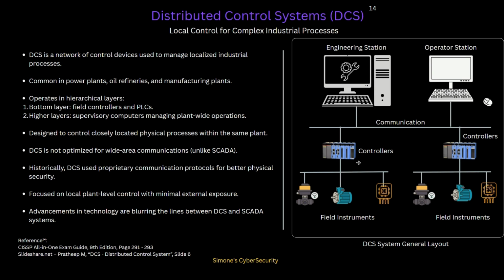Modern DCS systems are coming with features where you can control operations at a different site. Years ago there was a clear line: SCADA was used for distributed environments, wide area communications, and remote site supervisory control, and DCS was used in the localized environment.